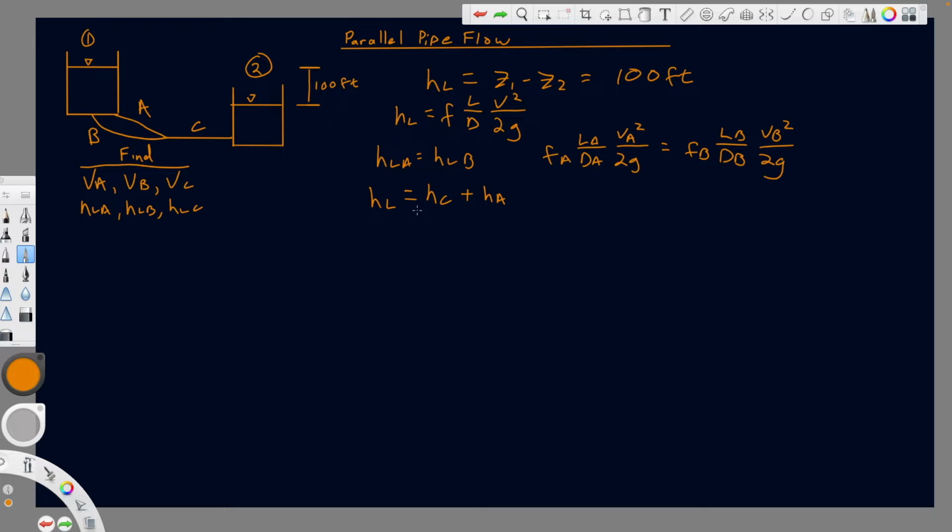Now there's one more relationship that we can draw on in order to kind of fill in the last piece of the puzzle here. And, you know, again, if you've been watching some of these videos or studied hydraulics, you probably know one of the relationships we almost always draw on is continuity, right? So we know that we have some total flow, which usually we just say Q, but any flow between these two reservoirs has to go through pipe C. So the flow rate in pipe C is going to be equal to the flow rate in pipe A plus the flow rate in pipe B, right?